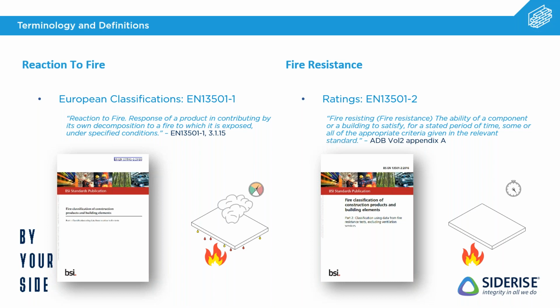Whereas with fire resistance, what we're looking at is, again, exposing the products to fire, but this time we're looking at how good the product is at blocking it. So rather than what it's doing and what it's producing, it's how well it stops that fire from transmitting through it. And there's a couple of different criteria that go along with that.